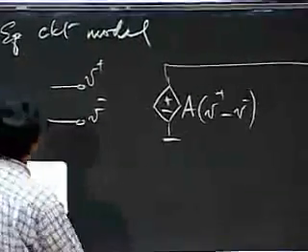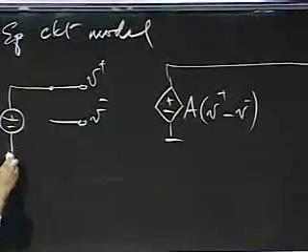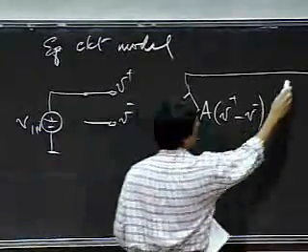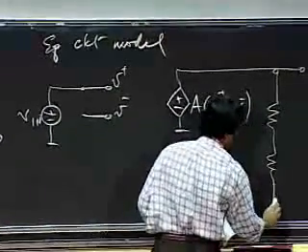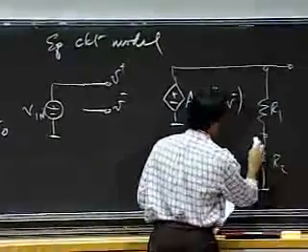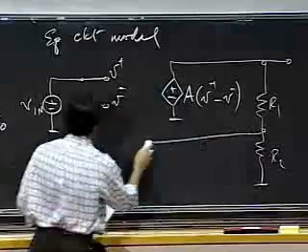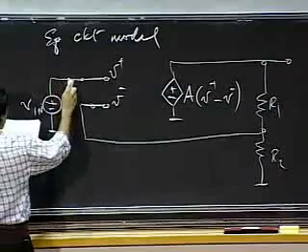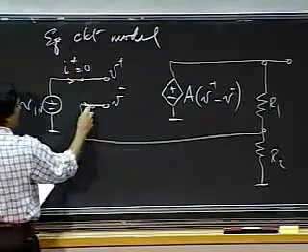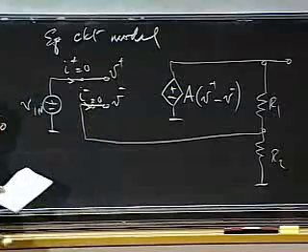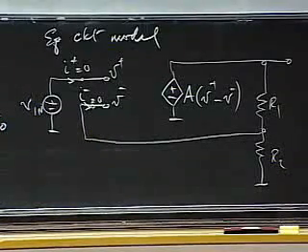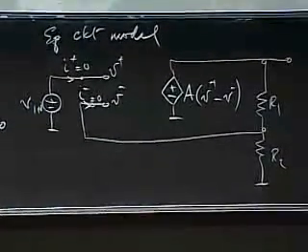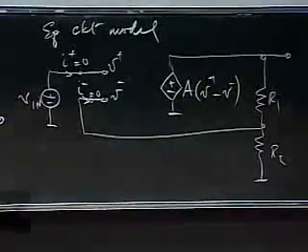And then I connect my V in here, and remember I have an R1, R2 resistive divider here, and this one gets connected to this terminal there. I also know that I plus is 0. I also know that I minus is 0. All I've done is simply replace the amplifier with its equivalent circuit. So let's go ahead and analyze that circuit now.